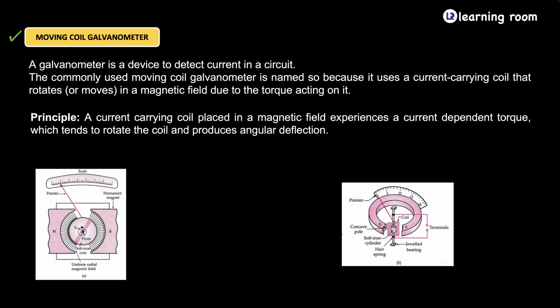When you reverse the polarity, the deflection should be exactly in the opposite direction. If it is not, the device is not working. Okay, so here I have some readings. For those who are online, see, this is how a galvanometer is going to be. The pointer will be exactly at the center. So I'm going to have some readings here.